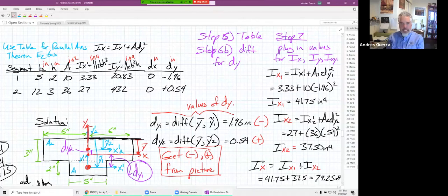That is a number we can take to the bank. That's the number we would use to calculate the deflection of that floor slab in Marquez Hall, in Coors Tech, or whatever project we're working on. So make sure you do each rectangle separately and then add them up at the end. Sorry I went over there.